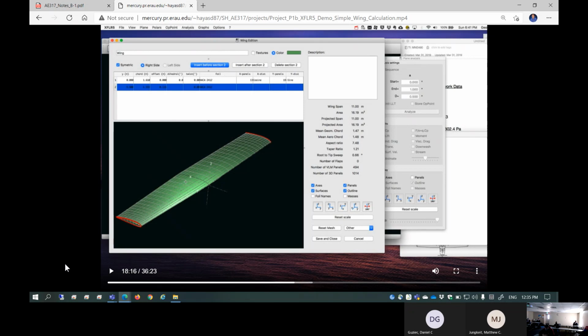In other words, 2D panel method is going to predict the 2D airfoil, and then 3D panel simply extends, stretches it out to design your wing. It's the most computationally intensive method, but you have freedom of lots of design choices. With lifting line theory, you cannot even put in the wing sweep. Each method comes with constraints, but I would recommend the 3D panel method. This guy's using VLM, but it's okay.